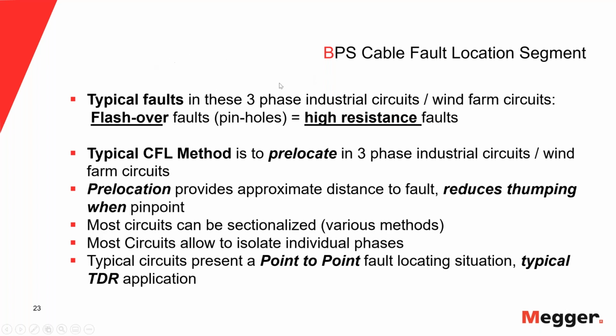Okay, so what are the typical faults that you have after going through the pre-screening? What are the typical faults we expect in three-phase circuits with solid dielectric cables? For the most part, those are flashover faults, high resistance faults.